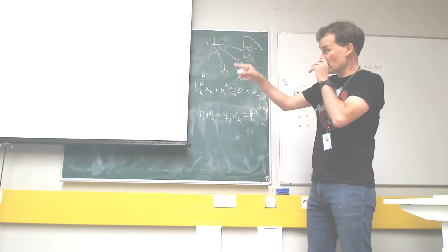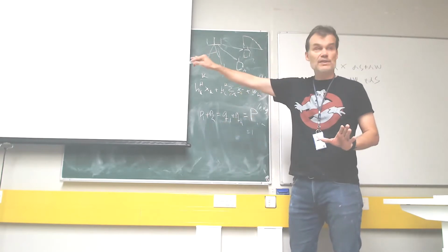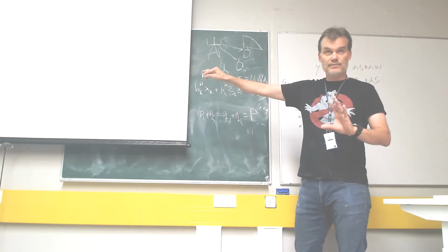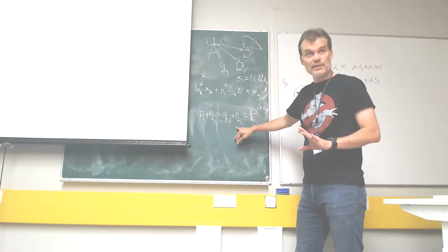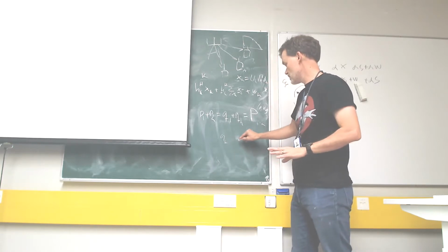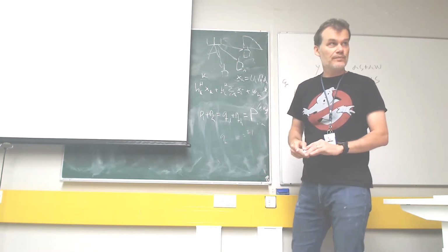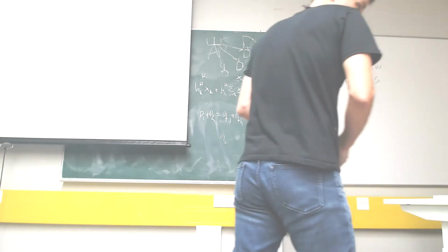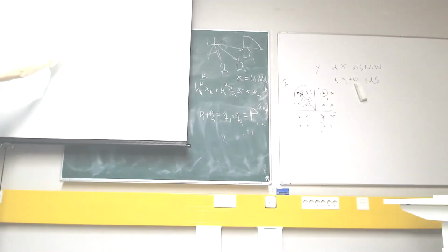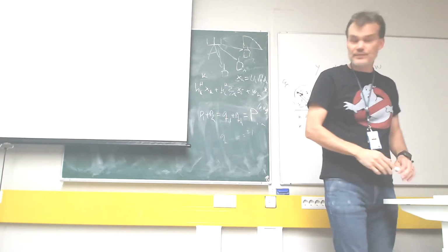What you need to do is make a grid, like here are 100 realizations of all these ratios. Generate a vector of Q1s and Q2s such that Q1 plus Q2 equals 1. Easy to do. For each pair Q1 and Q2 for fixed channels, you generate a pentagon, and then you just plot those pentagons on top of each other, and this is what you get.